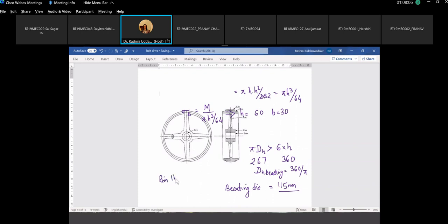for light duty is 0.25 times root over d plus 1.5. Similarly, the crowning, this part, the crowning is given as 1 mm in a 100 mm face width. So depending upon the face width depends upon the width of the belt. Normally the face width is taken as the width of the belt, a little more than that. And accordingly we find out what is the crown.